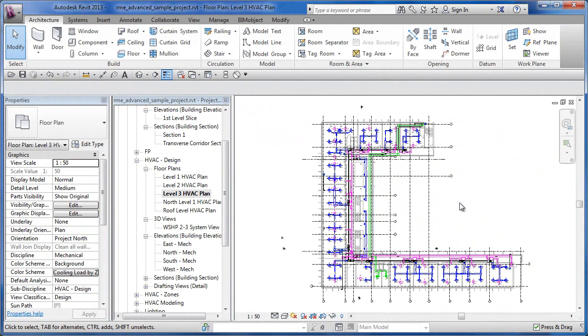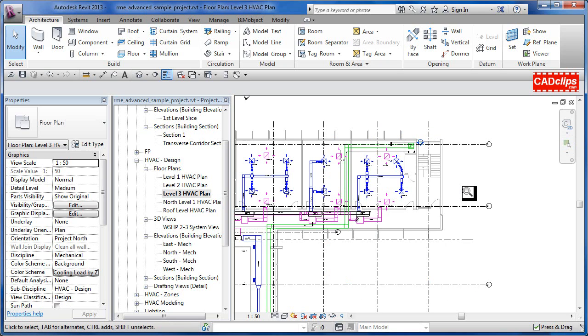In this lesson, I just want to do an overview of grid lines. It doesn't really matter what you draw, you really should use grid lines. You don't have to see them or print them or plot them, and you can make them look just about any way you want. But you really should have them, and especially everyone knows the structural stuff tends to tie to it.